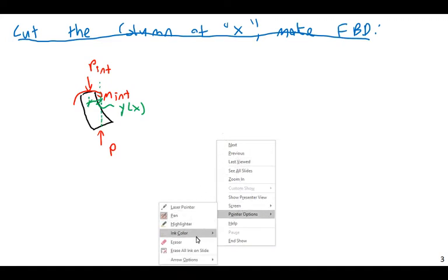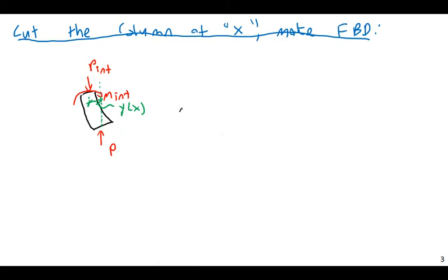First of all, if I do a summation of forces, well, that's fairly straightforward. Summation of forces in the X direction, to be consistent with what I've done previously: the sum of forces in the X direction equals 0. So therefore, the internal P at that point must be equal to the end load P. Not really any surprise there. Then if I do a sum of moments at the bottom, basically this means that I'm going to have 0 moment overall.